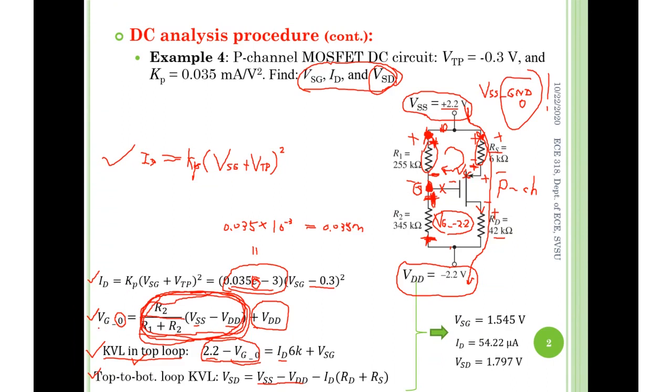So how to find the voltage from the gate with respect to the ground? You need to add up your original reference, negative 2.2, the bottom here. Add, not subtract. You only tack on that if it's with respect to the ground. You're basically just making an adjustment by adding the plus VDD. Yes. So that you can find it with respect to the ground.